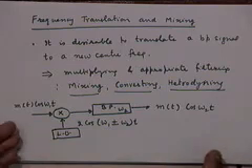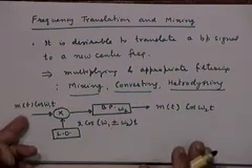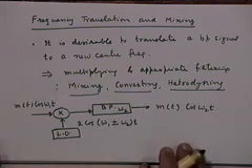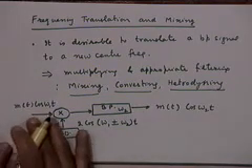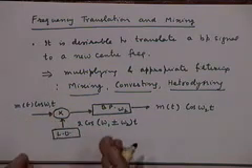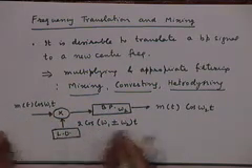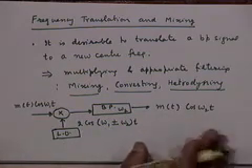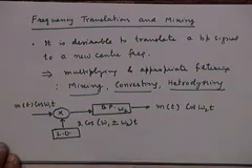As an exercise, please check that if instead of m(t) cos(ω1t) I had taken the more general representation of the bandpass signal, that is m(t) cos(ω1t) with some in-phase component and some quadrature phase component, and do this process, we will still get the translation intact, right? I'll leave that as an exercise.